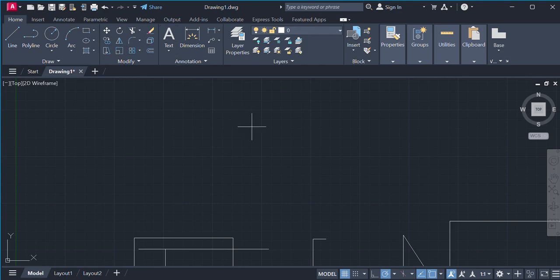Center to radius, you can click on it. First, you look on your command box. It will tell you to specify the center point for your circle. Then you specify a point anywhere in South Africa. Then it's going to ask you to specify a radius. Then we can specify a radius of 1,000. Enter. Then it draws a perfect circle on there for you.